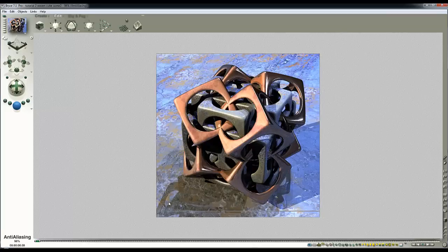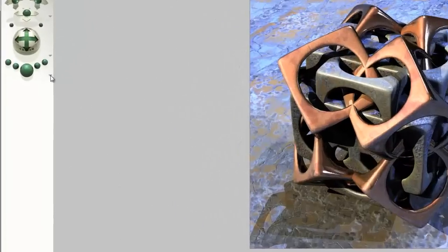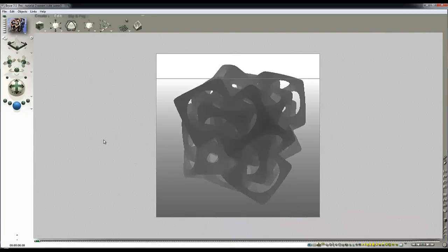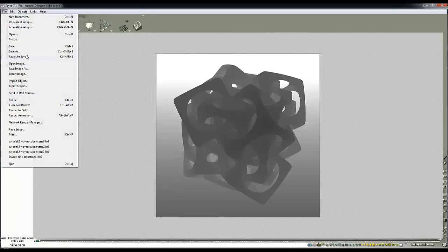Okay, right, it's nearly come to an end now. So I'm going to save that as, File, Save As, and it will increment it to 3 there for me. So that's saved. Just let that save, and then we can select from here the render options. We can use distance mask, see how that looks. So with this now, what it's doing is it's giving us white for things that are further away and darker for things that are closer. So File, and we'll just save image.